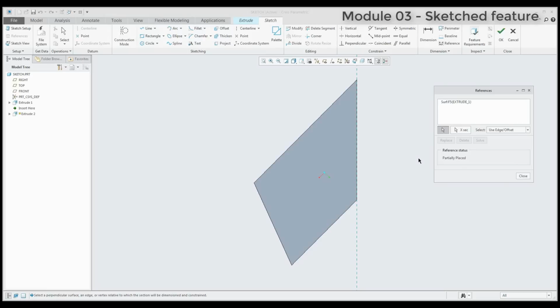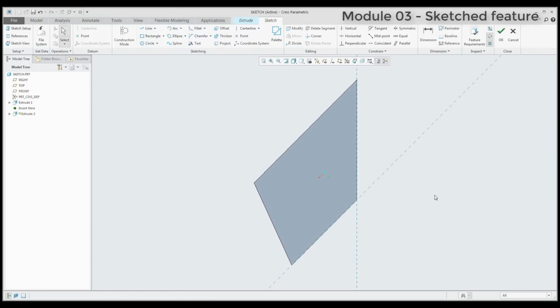Directly, if you finish the sketch orientation, the system will select some references. And you know that in the sketch it is necessary to specify the references if you would like to attach some lines, arcs, circles, and so on to a sketch. So right now, the system will select this button, References, and you can add other references. You can add as many references as you need in your sketch. And the question is, what are these references good for?